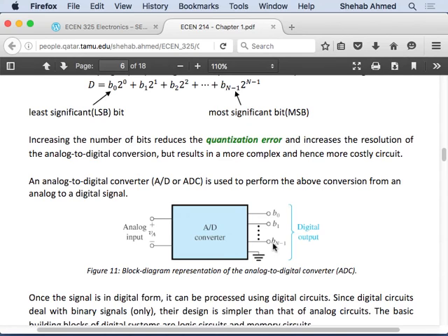So maybe there's a position sensor. Again, I don't know how the mouse is constructed, but there's probably something that is measuring the number of rotations in the X direction, and the number of rotations in the Y direction. This can be analog or can be digital. It can be digital because there are sensors called Hall effect sensors. Hall effect sensors produce a pulse, for example, every rotation. So I can be counting these pulses, and producing, okay, in X I moved this number of pulses, and in Y I moved this number of pulses. So we need to look at the design.